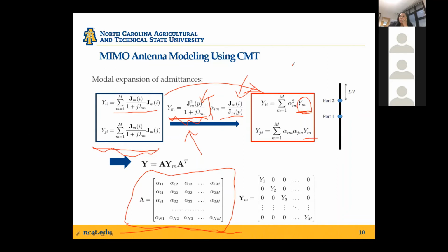But if you are using a ladder network, it is frequency independent, or a wideband network. A ladder network? Oh, I see. Why I'm saying this is that many of the decoupling networks available in the literature use LC networks, which decouple those things. They are very popular. Yeah, I'm aware of some of them working as well.